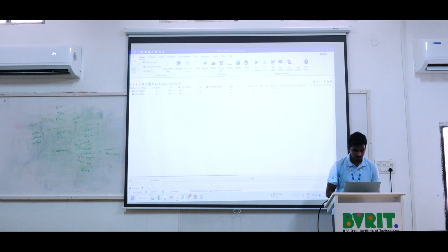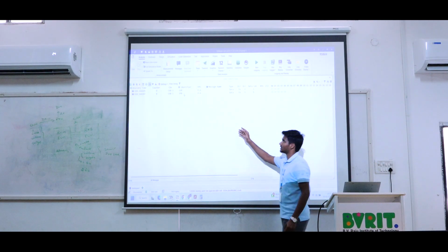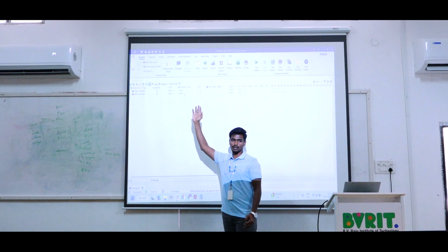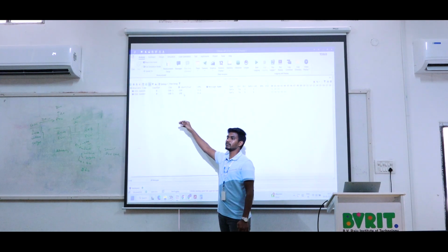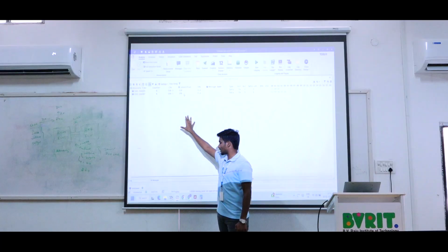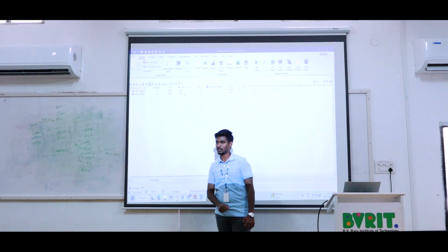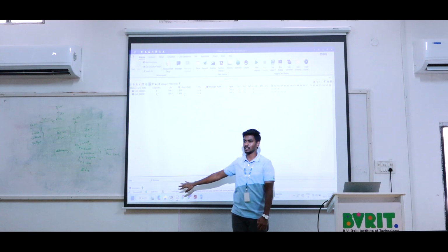So now it shows only ID number 120, but we don't know which ID it is. Is ID number 120 the engine ID or the transmission ID? Where it is transmitted, where it is received, we don't know anything. So that is the mapping they have definitely created in the CAN database. That is the purpose of the CAN database.